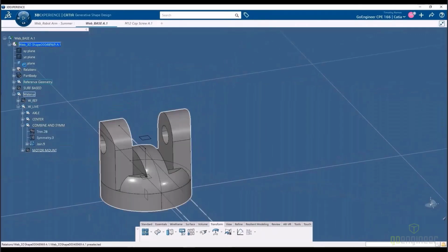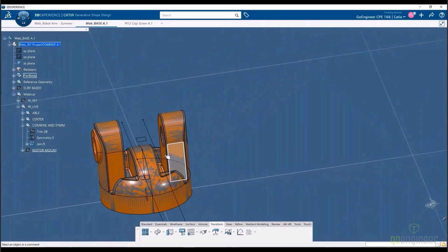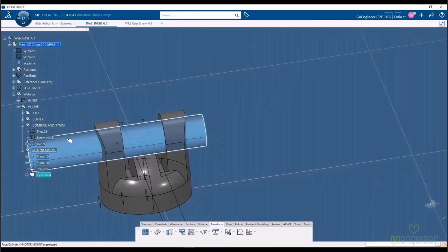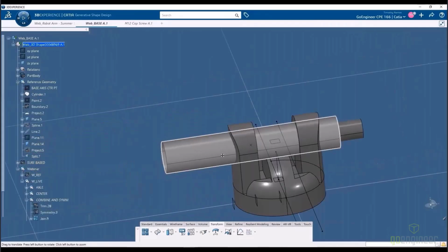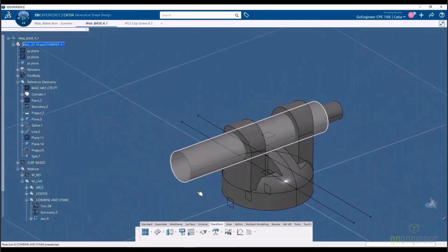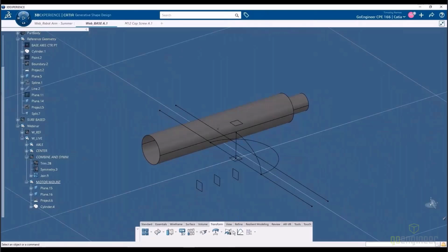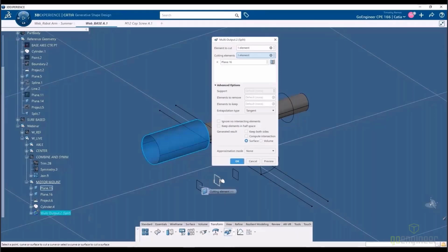Now comparing this to our final model, on the left-hand side here we see this cylindrical surface used to mount our motor on that axle. So here I'm going to build that geometry and use my Boolean commands to insert it into the final volume at the end. Here we have our reference cylinders that represent the outer and inner diameters of our motor mount. And I'm going to use my split command to reduce the size of these cylinders so that they'll sufficiently fit in our model.